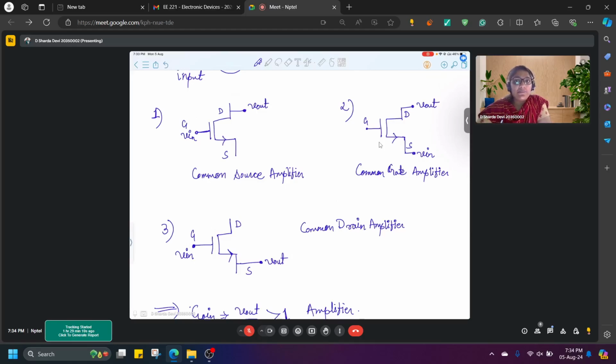I'm not talking about decibels, okay? I'm talking about volt by volt gain. If you have a negative volt by volt gain or negative current by current gain, that means there is a phase shift of 180 degrees. Am I clear? Yes, ma'am.